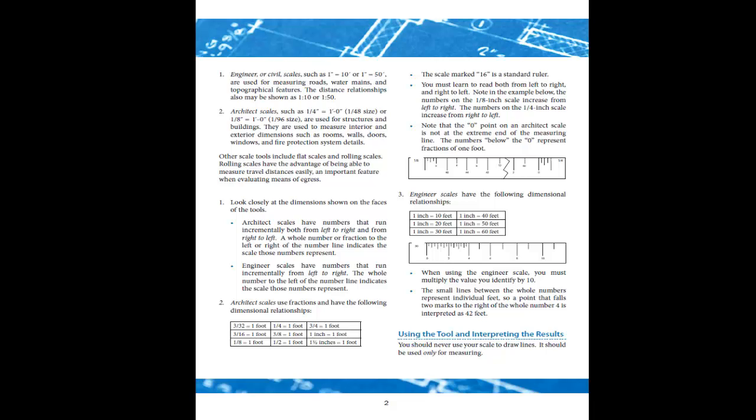We also have two different types of scales: fully divided scales and partially divided scales. One of the things I recommended in the email I sent out prior to this was that you should pick up a 3-sided engineering scale and a 3-sided architect scale, so we can use them on our paper and learn. We're going to have some exercises where we need to scale line lengths and dimensions on the screen. A civil engineering scale that is base 10 is fully divided. Everything is divided all the way across. In an architect scale, it's only partially divided.